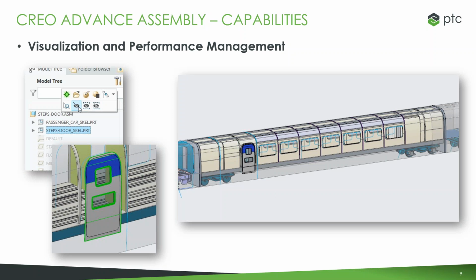So that way, when you open those subsystems, you don't have to have other subassemblies open just to reference parts or surfaces that might be in there. You can actually bring that reference right into the one you're working in. So only have the data open that you need to work with, as well as using lightweight representations and shrink wrap. So external shrink wrap geometry reduces load time and increases system performance.